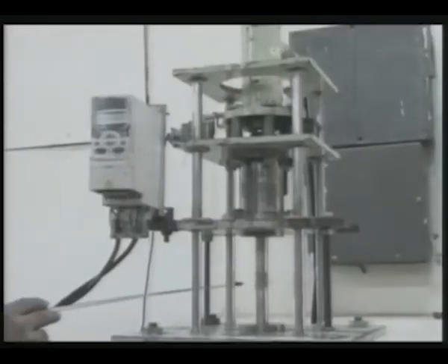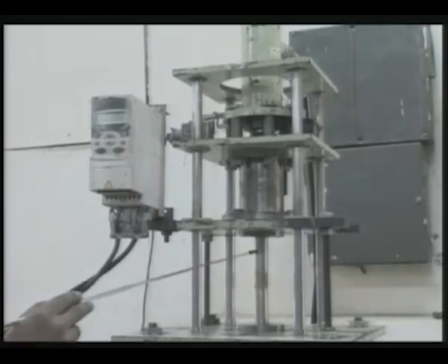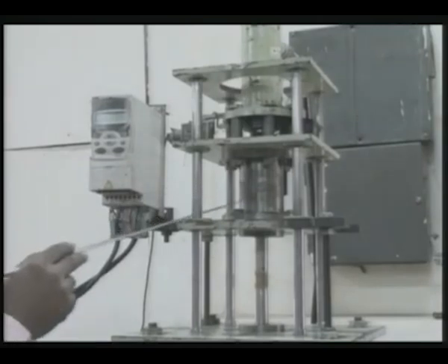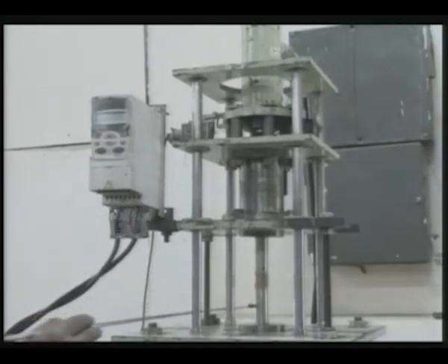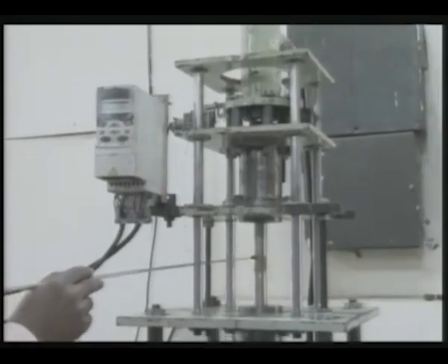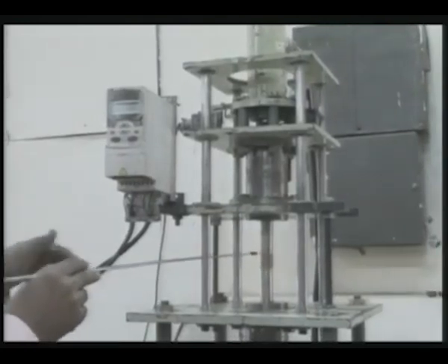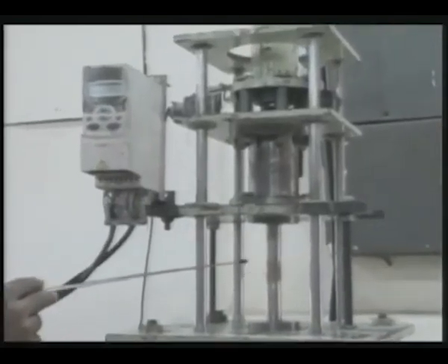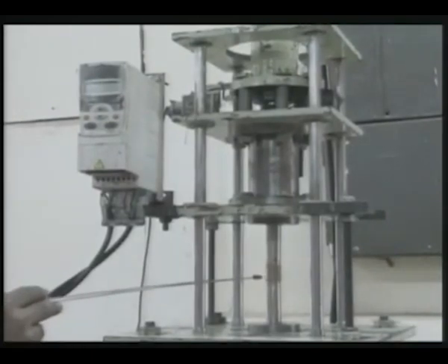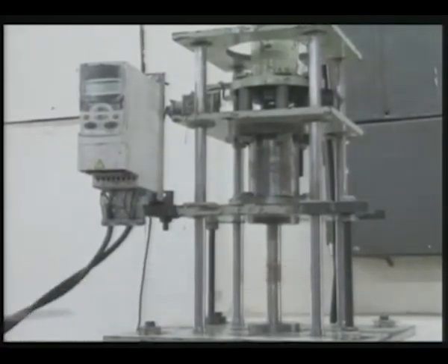This is the workpiece fixture of the MRFA process. It has two parts. One part is the top guiding attachment which is connected to the top media cylinder, and another part is the bottom guiding attachment which is connected to the bottom media cylinder. Inside these two guiding attachments, one brass fixture is attached, and inside this brass fixture 4 internal slots are there where flat workpieces are kept, and electromagnet coils are attached at these 2 points.